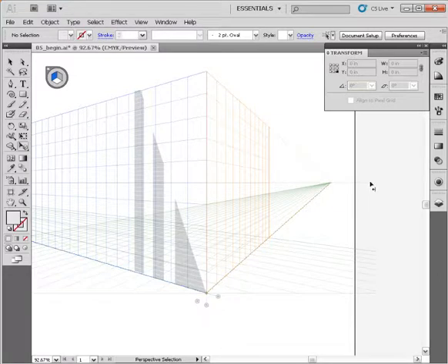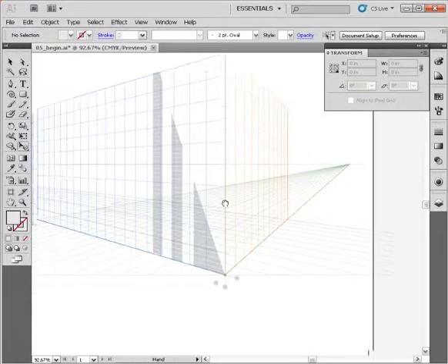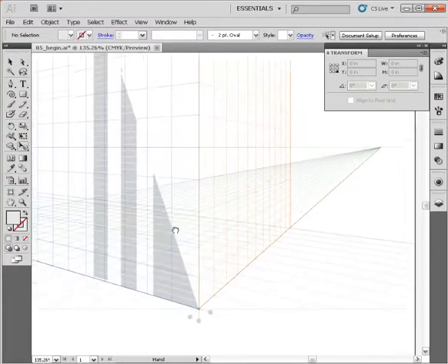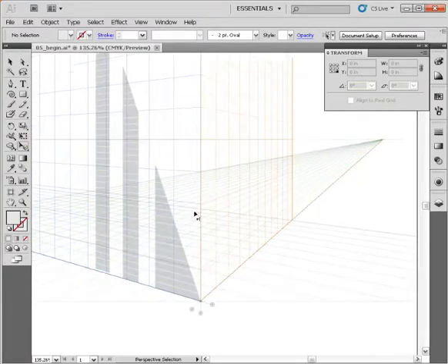Now if your perspective grid has a different scale setting, you're going to have to do some math here. So just fair warning when you do this next step. If it doesn't come out looking exactly like mine, keep in mind you may have the scale set to something besides 1 to 1. So I tell you what we're going to need to do is we're going to basically need to move this left grid plane back that specified distance so we can create this new plane.